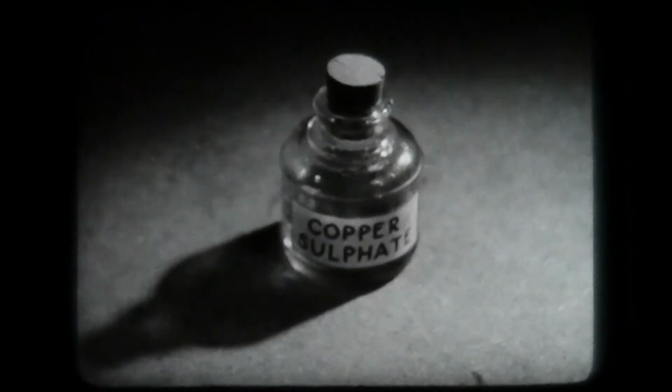Another application of the steel rule is in the combination square. Among its many other functions, the combination square is used in laying out work. If the material is of steel, a solution may be used to make layout lines more easily visible. Using a rag that is free of oil or grease, swab the work sparingly with the solution.